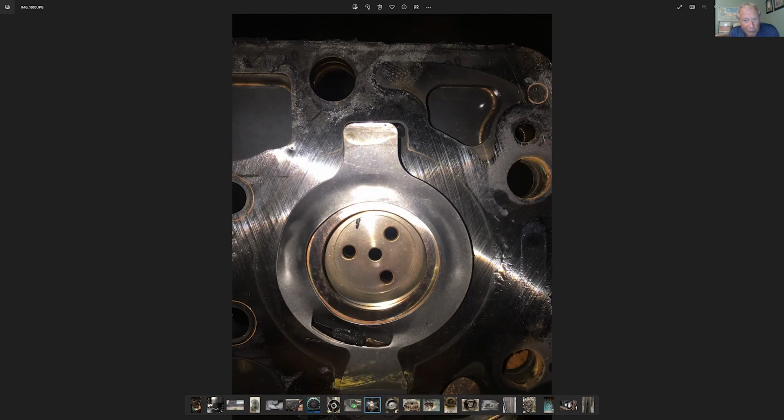But yeah, slugging and flooded start and crankcase heaters, I think, are one of the things that are there. They have voltage to them, but undo the voltage, shut your power off to it and ohm that thing out and make sure it's still doing what it should do. Some of the smaller compressors, you can kind of feel if the crankcase heater is on. And some manufacturers will run the crankcase heater only when the compressor's off, and not necessarily when it's on.